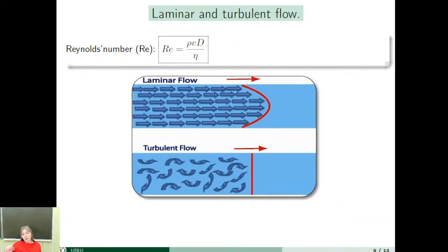And then let's talk about laminar and turbulent flow. If each fluid layer slips over the other and different layers do not get mixed, then the flow is called laminar. The velocity of flow at any point of the fluid remains stable. The streamlines do not intersect each other.